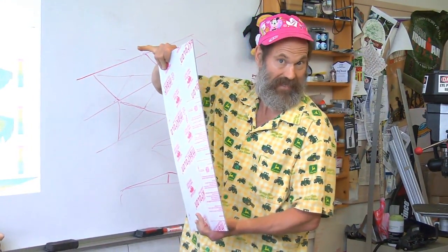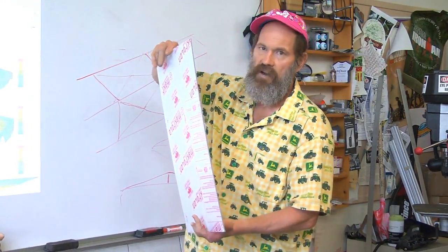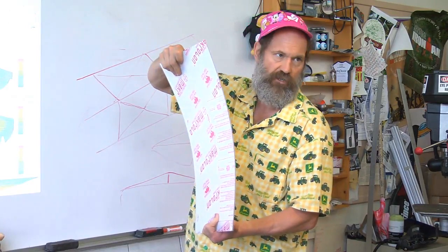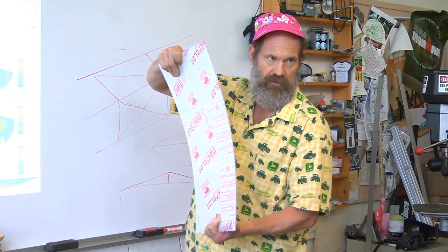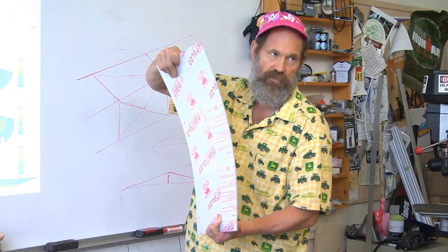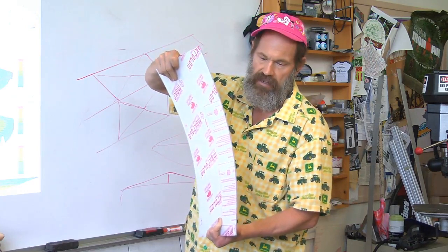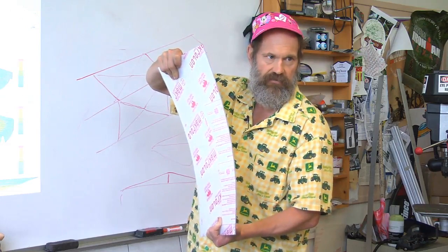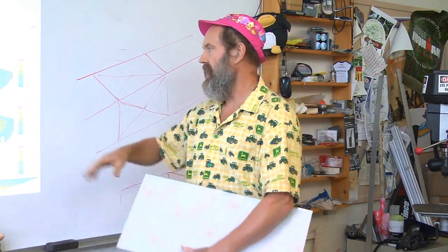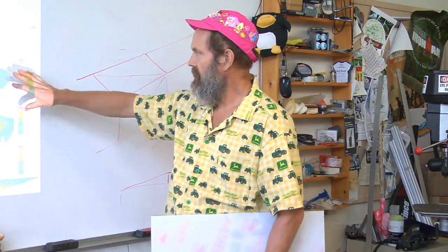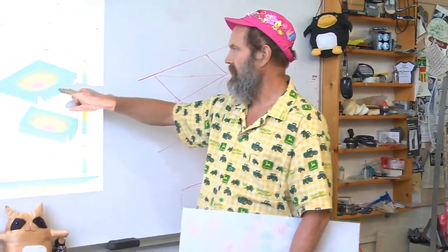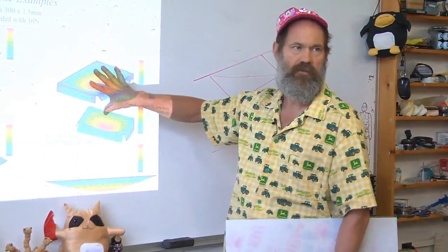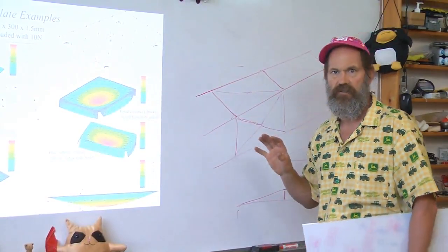Remember, we're going back to that stability discussion. You often want to bias things in one direction or the other, toward the particular mode shape that you're trying to quench or stop, and leave it there. Now it's much, much more stable and stiff. So you can discover that doing your finite element analysis, looking at adding ribs or pre-displacing structures to get a very much higher degree of stiffness.